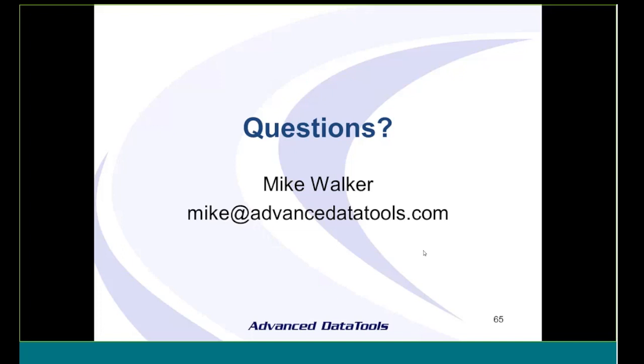And then you need the gateway, and you can get a Raspberry Pi or the Beaglebone as I used, and you could start off just by wiring it directly in, and then very easily you could have a simple temperature sensor sending your data to your Beaglebone or your Raspberry Pi, and then you could install the database on that and start storing that. So you could get up and running very easily.